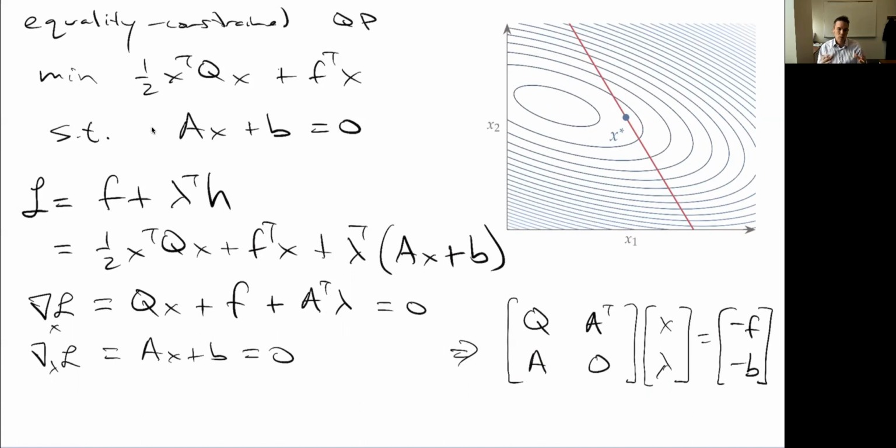But we intentionally approximate our objective as quadratic, and we do that because we can solve this very efficiently. As long as Q is positive definite, it'll be convex, meaning it has one solution, and we'll find that global optimum really quickly and efficiently. And so that can be very advantageous for controls applications where we need to solve an optimization problem again and again and again repeatedly as we get new information.